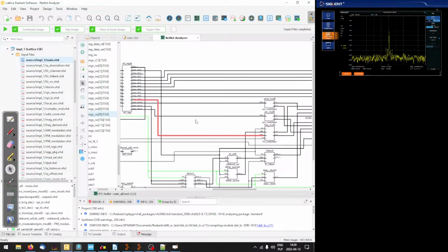And before we generate the tone, we actually have to know which tone to use. And if there are 50 tones available, we also want to have one additional tone that's going to have value of 0. So that's going to disable the CTCSS if we don't need it.